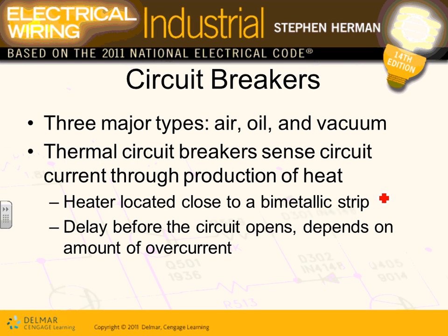The only thing you need to know, guys, is that it's required on 1,000 amps or more. So, Adam, we have our services and feeders and branch circuits. Now the building that we have, guys, is 4,000 amps. So in a 4,000 amp building, you are required to put in ground fault protection, one ground fault protection.